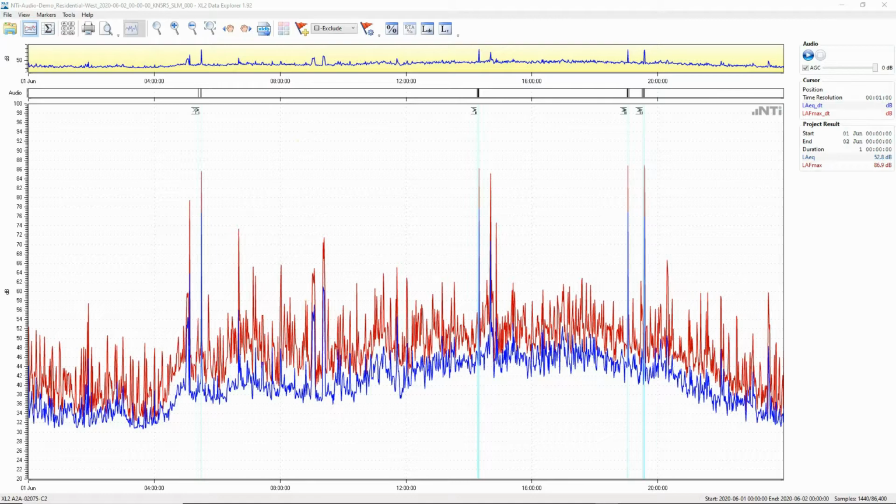I'll show you how. The steps that follow demonstrate data formatting features of the Data Explorer and show you how to customize the report to suit your style. We see a graph of the results of the 1 second logging with 10 second audio recordings associated with the spikes. These indicate periods of high sound pressure.